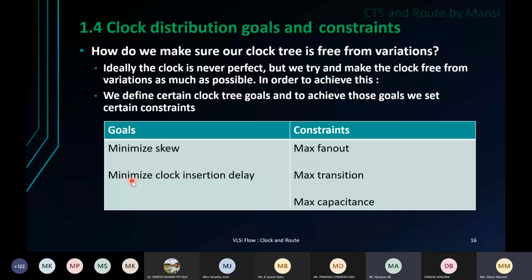The one which has 100 buffers in the chain will end up having a more disturbed clock signal in the design. So you make sure that, okay, I want to reach my design from the PLL. Let's say my PLL is sitting over here. This is my whole SoC, system on chip. My block is this one. My PLL is sitting at the corner. What do I try?